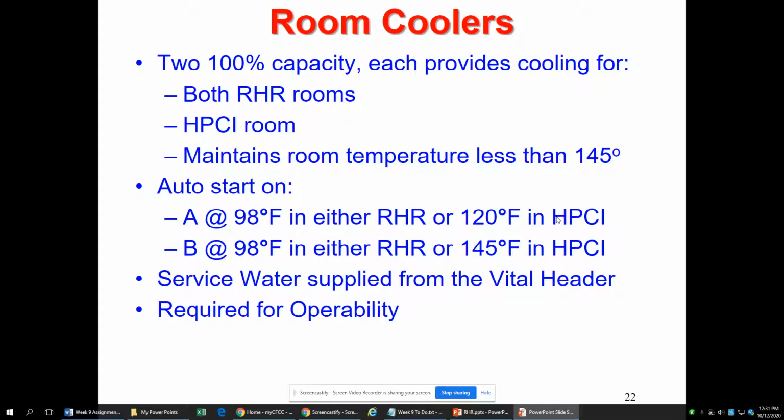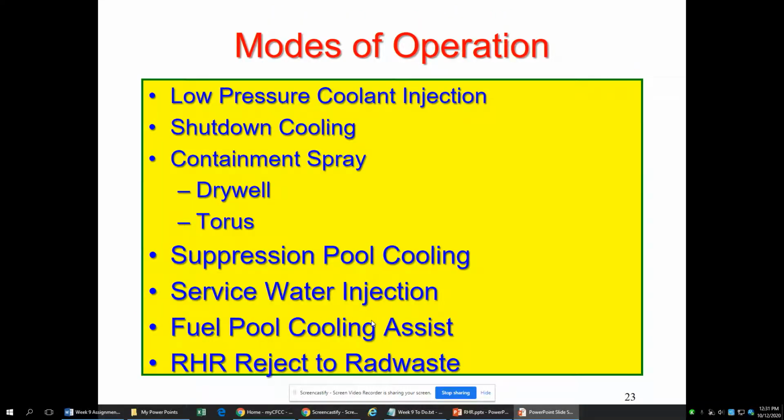There's room coolers. If these things run for a long time, the rooms are going to start to get hot. And the famous band 98 Degrees, this one is an easy one to remember for anybody from the 90s. So if the room gets too hot, these things are going to kick on and it's going to keep the room cool. And it's the same system as the others where there's just some service water and we blow a fan over it. And you have to have these room coolers.